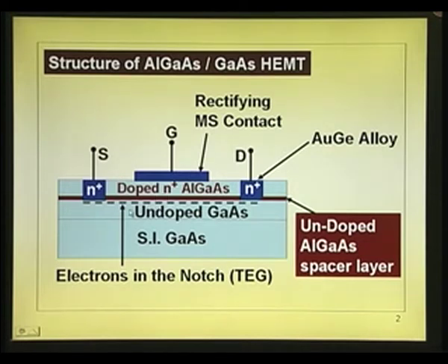We do not want them anywhere near these impurity atoms. So, put a spacer layer which spatially separates the donors. Spacer layer separates the donors physically from these ions. Absolutely no contact, no Coulombic force of attraction, no scattering because of that. So, that is why I put it.